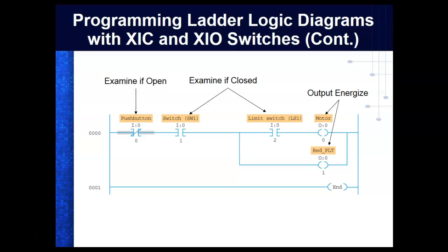But when you're in this diagram and you come over here and you see something that looks like this, that's a normally closed limit switch. What are you going to use in your program? Examine if open. That's exactly right.